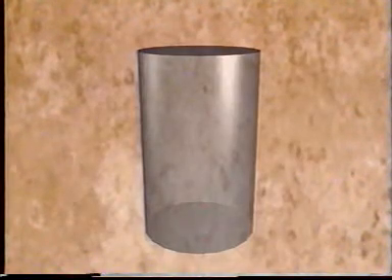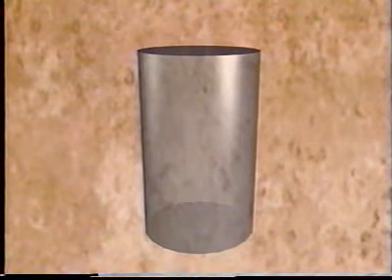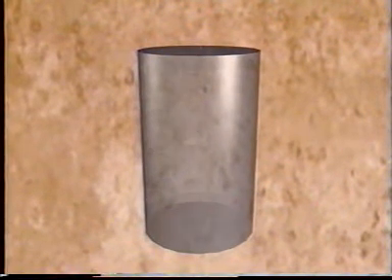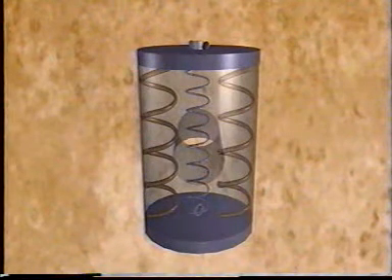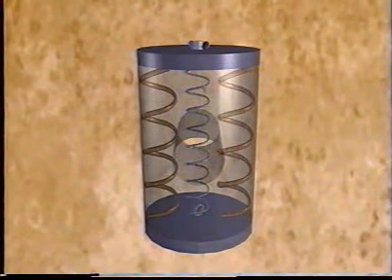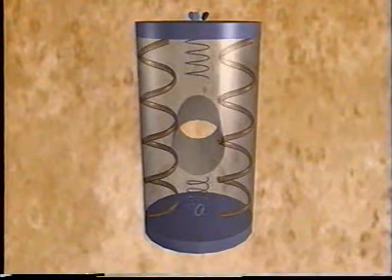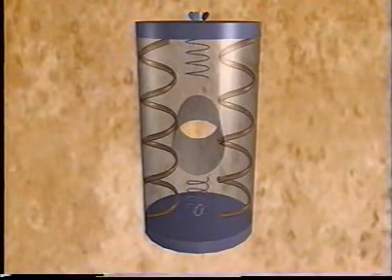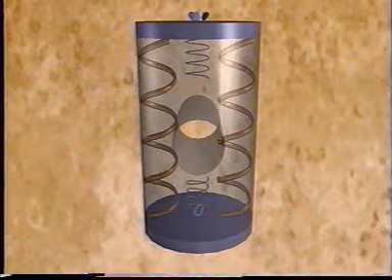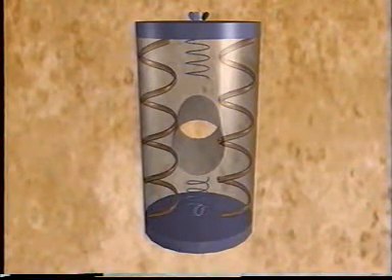Suppose we have a bar with a longitudinal residual stress system of compressive external and tensile internal stresses. If a hole is drilled through the length of the bar, the internal tensile stress will be relieved. To balance the system, the external compressive stresses will be permitted to relax. As the compression stresses relax, the bar will get longer.